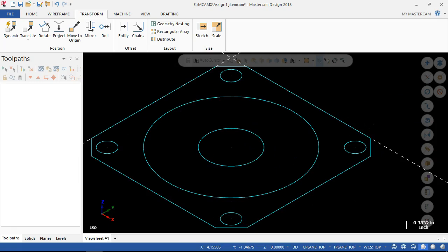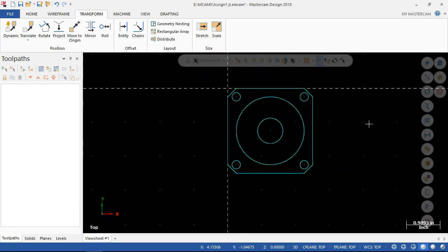Isometric is going to be handy when we go to preview the toolpaths, when we start looking at depths and double checking our numbers, because it's easy to make mistakes and leave positives and not get negatives, and if you miss that sign, then we're going to see the toolpath floating around above the part. So the two that you really need to remember are Alt-1 and Alt-7. So that kind of centers it on the screen.